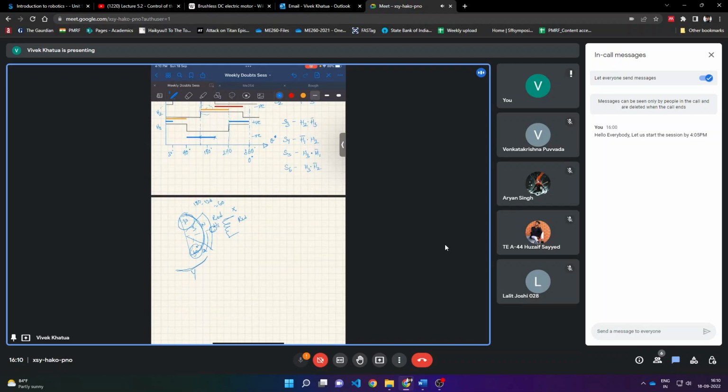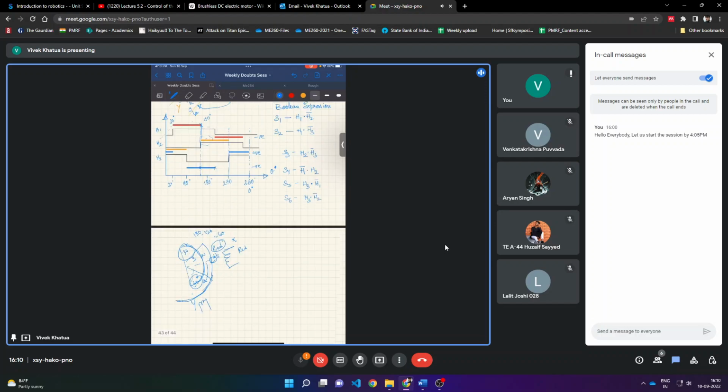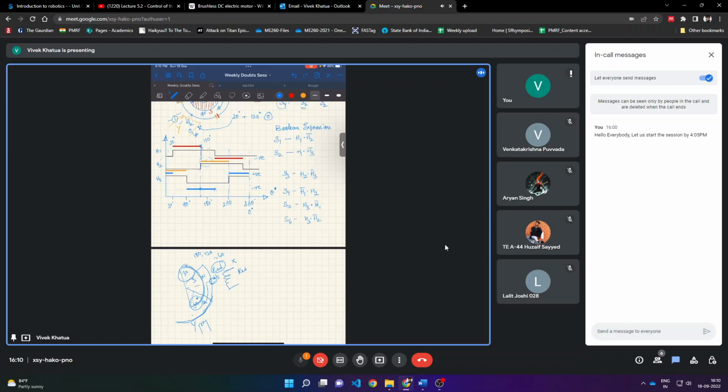So now when I switch on the yellow phase, it will attract this north and bring this entire pole here, given that red is switched off. If that is not, it's going to come somewhere in between and be stuck. So that is where these Boolean expressions cannot be malleable, right?